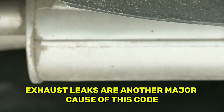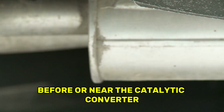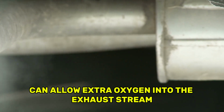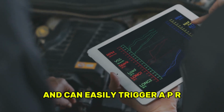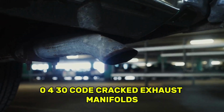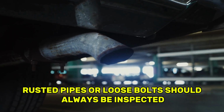Exhaust leaks are another major cause of this code. Even a small exhaust leak before or near the catalytic converter can allow extra oxygen into the exhaust stream. This additional oxygen affects sensor readings and can easily trigger a P0430 code. Cracked exhaust manifolds, leaking gaskets, rusted pipes, or loose bolts should always be inspected.